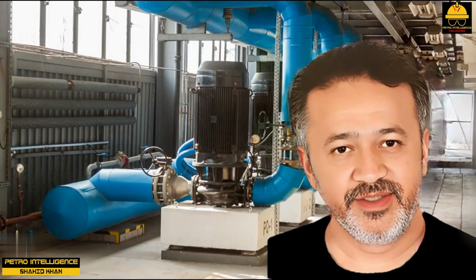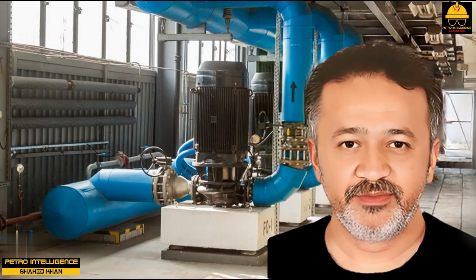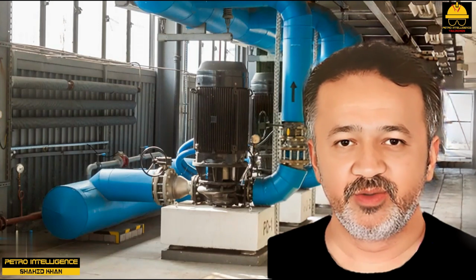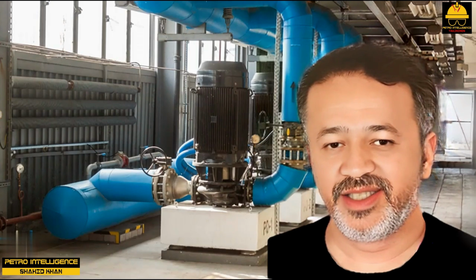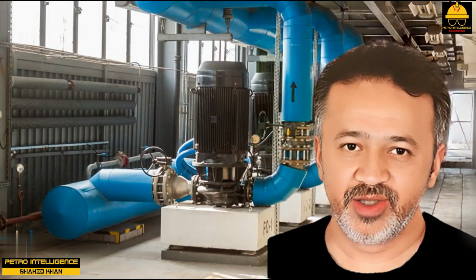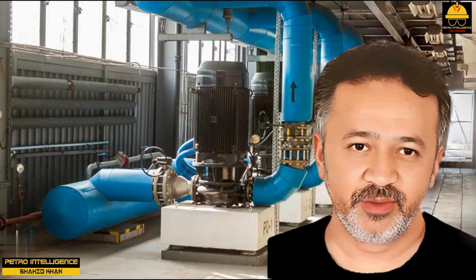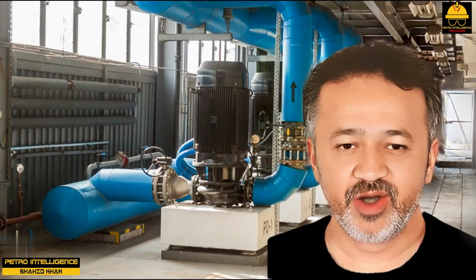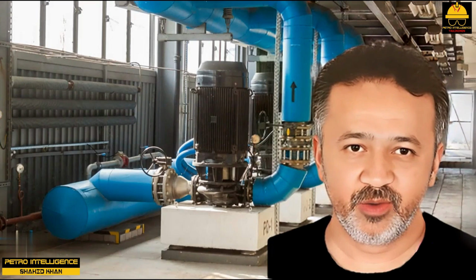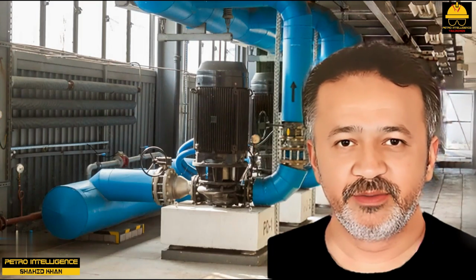Momentum. If the length of the pipeline had been a few hundred feet, this incident would not have happened. It is not only the sudden reduction of the velocity of the water that caused an increase of the water level in the sump. It is also the mass of water in the 3-mile pipeline that contributed to the increased height of water in the sump. The combined effect of mass times velocity is called momentum. The mass of water in our pipeline weighed 160 by 10^6 pounds. This much water, moving at 8 feet per second, represents a tremendous amount of energy, about 500 million BTU per hour.